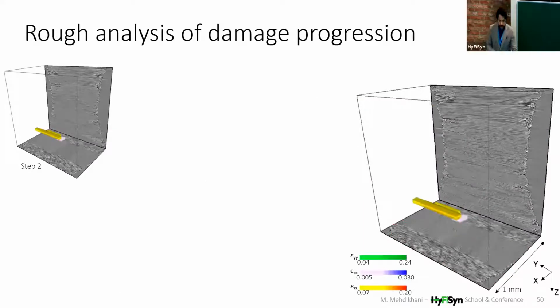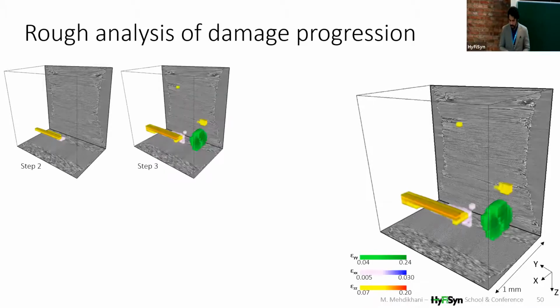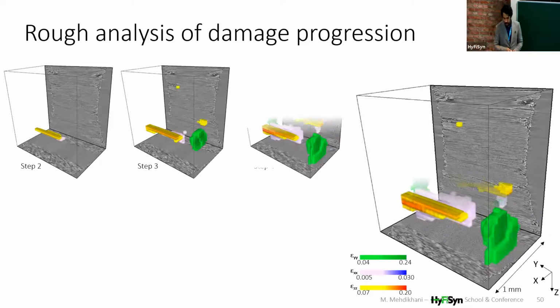This is the result of the local or subset-based DVC. We can see that here in this transverse ply, the first transverse crack is detected. And once we continue the loading, a form of delamination appears here at this transverse crack, and then some apparent fiber splitting is visible.